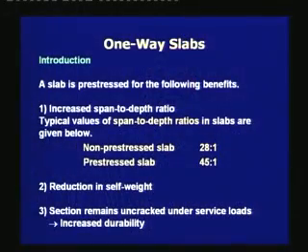A slab is prestressed for the following benefits. First, it is the increased span to depth ratio. Typical values of span to depth ratios in slabs are given below. For non-prestressed slab, the span to depth ratio is 28:1. For the prestressed slab, it is 45:1.